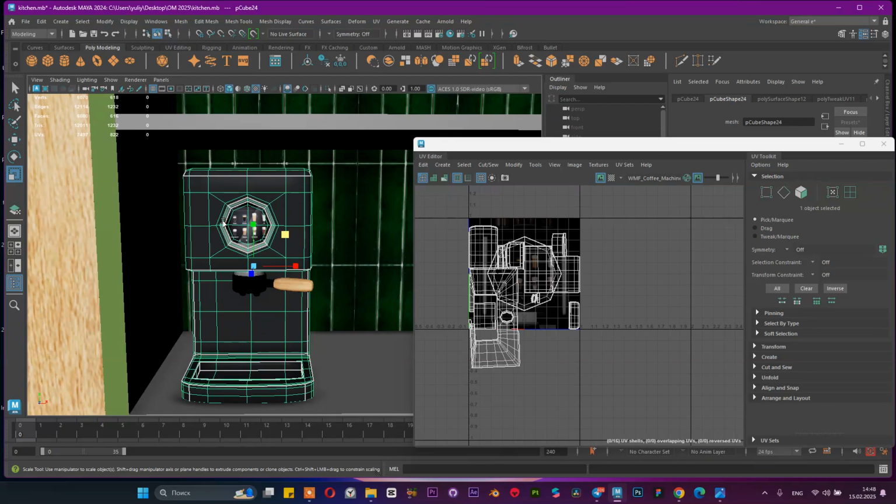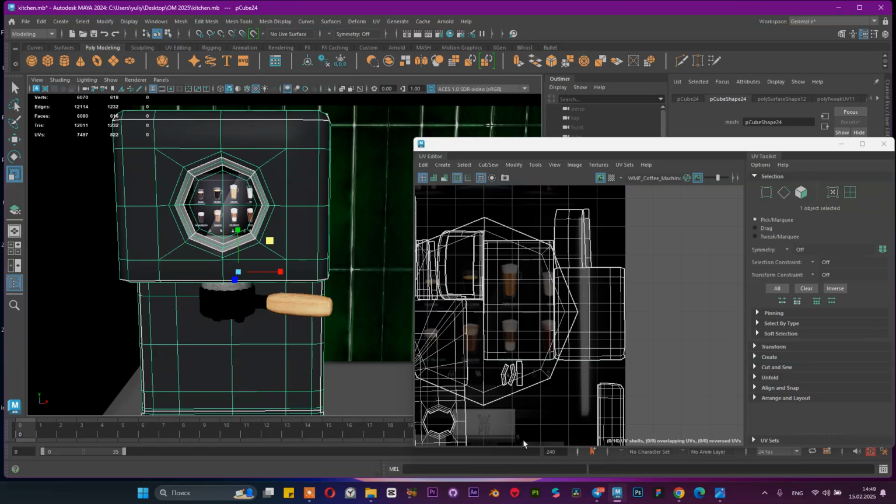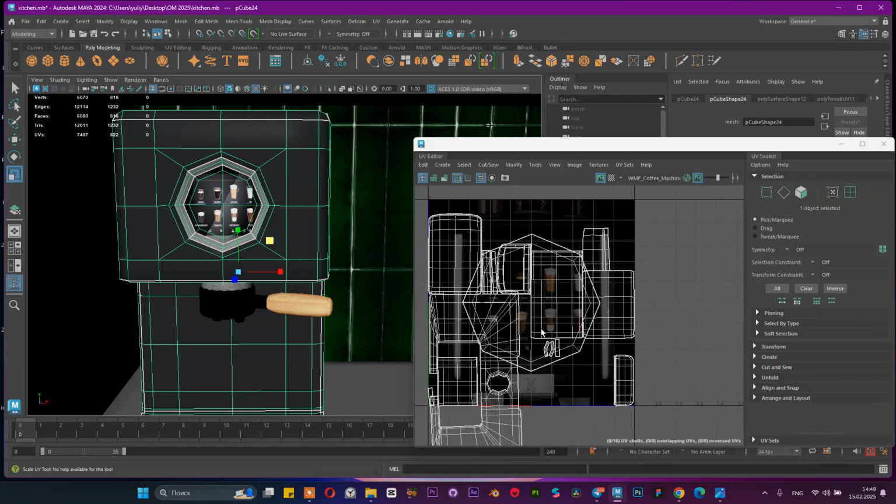And in the second stage, we are going to use Substance Painter or 3D-Coat for creating the same complicated materials, but in one material. We are going to use some masks for this, create a better UV layout, and sometimes use Photoshop to put these detailed images into one material.